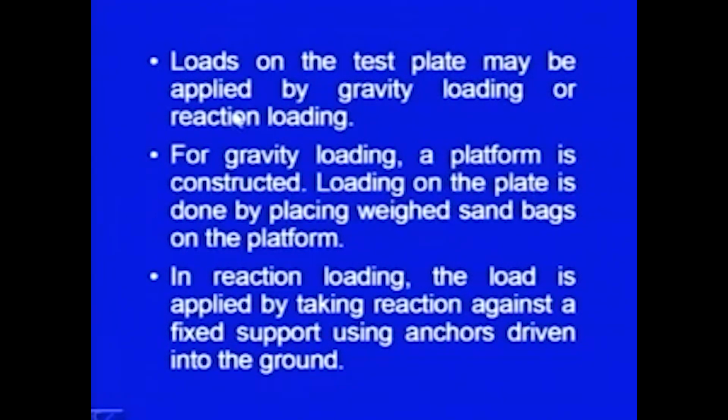Gravity loading, it is clear from its name, means it is deriving the force out of gravity, out of its weight. So, what is done is a platform is constructed, and on that platform generally sandbags are placed. Using these sandbags, there will be weight of sandbags, using which the load can be applied.